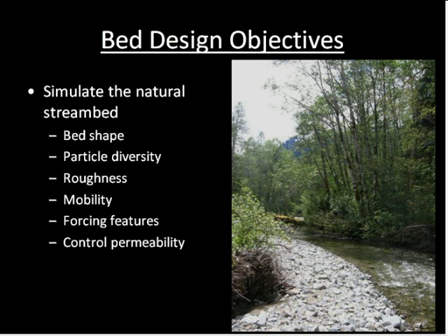There's an awful lot of substrate analysis methods out there. The one you use is likely going to be a function of familiarity, maybe regional calibration or ease of use. But whatever method you choose, I would suggest that it's important to account for bed shape and particle diversity.